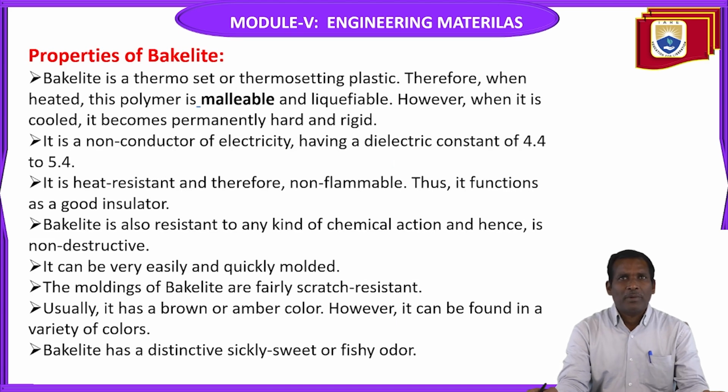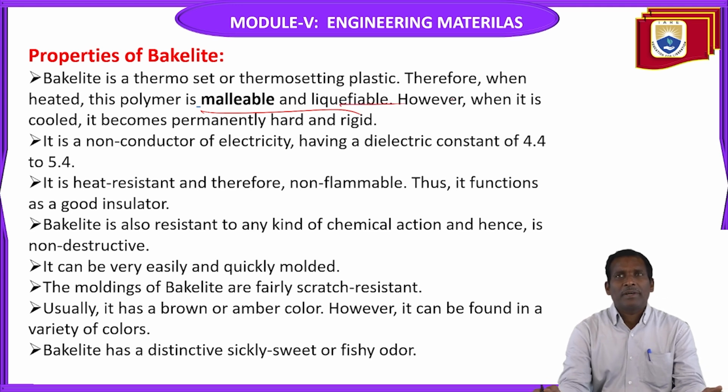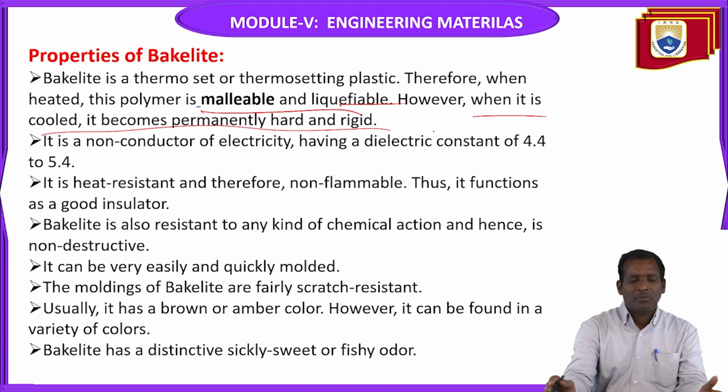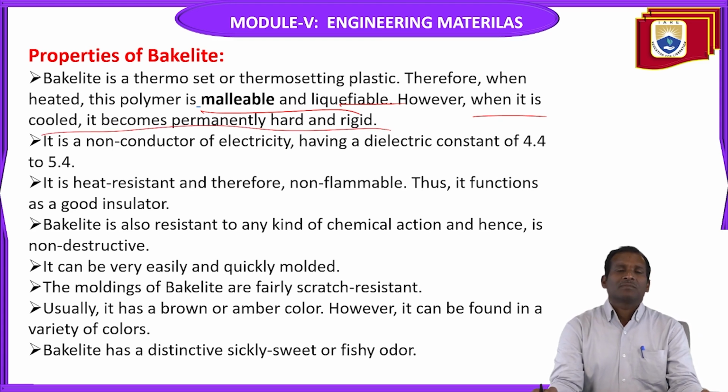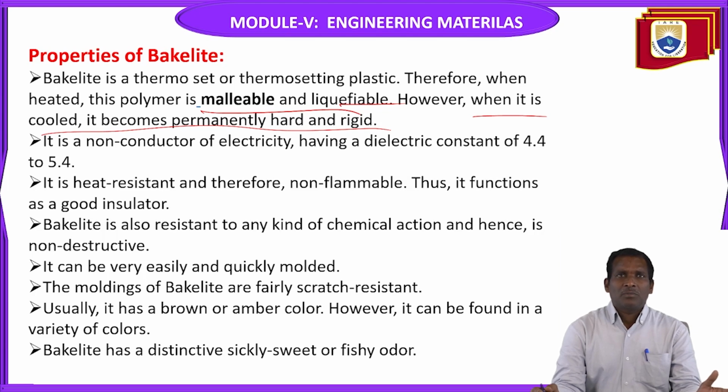Now, what are the properties of bakelite? Bakelite is a thermoset, or thermosetting plastic, as I already told you. When heated, this polymer is malleable and liquefiable. However, when it is cooled, it becomes permanently hard and rigid, not temporarily. That's why this polymer has that property.